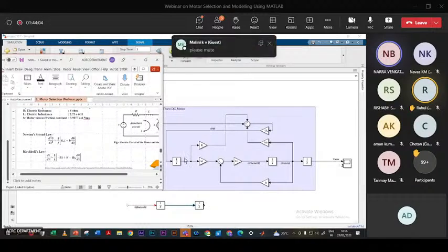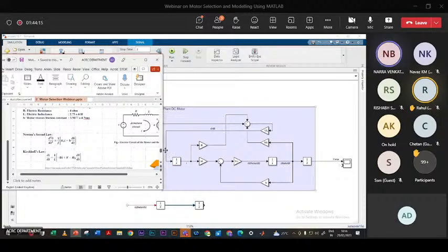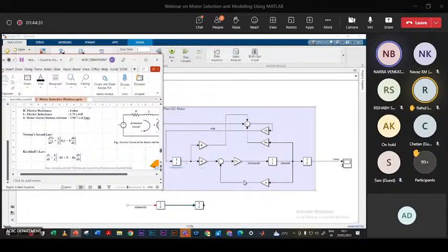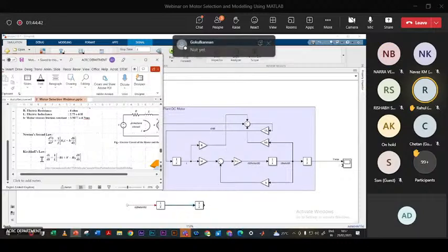So di by dt. I again use that, like I have observed, I make here I, and I use an integrator before that. Before that line I have here di by dt, because I want the di by dt from the Kirchhoff law. So I simply use this kt into I and I got this equation. So overall, this Newton's second law, the rotor position part, is here. Then I forward to the Kirchhoff's law.